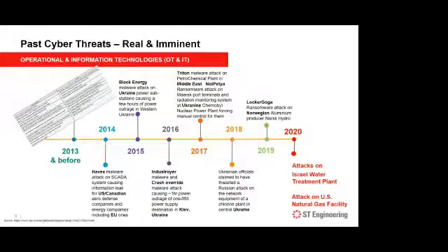The Stuxnet attack back in year 2010 is a classic example of an internal threat, where the employee actually plugged in an infected thumb drive into the OT environment. Subsequently, the malware took control of the assets, and thereafter it varies the gas separation device at extreme rotational speed, causing it to break down.